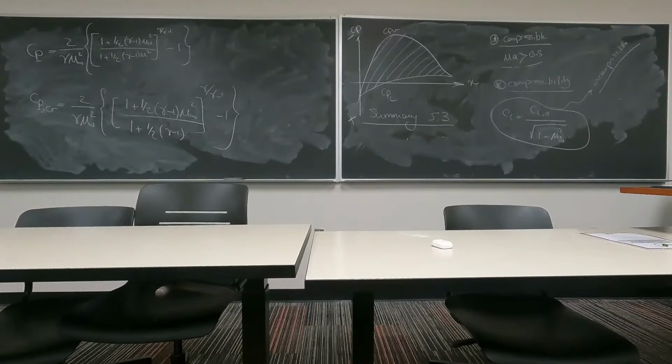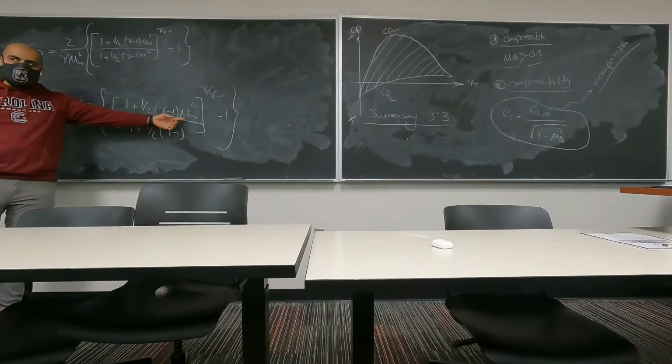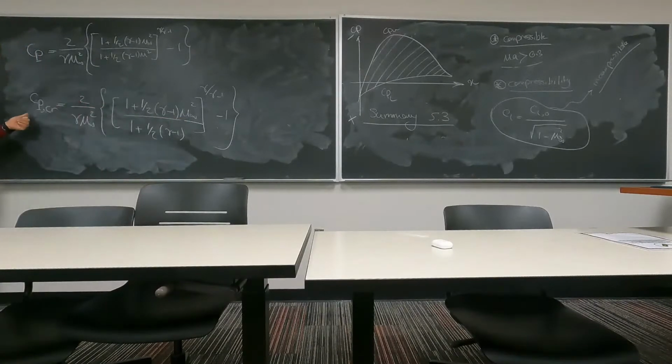So how can we find the critical Mach number? We essentially want to go about this the other way around, right? Here, using an M infinity, we found a critical pressure. To go about it from the other way, we have to find a minimum pressure on an airfoil, and then using that, we need to find the critical Mach number.